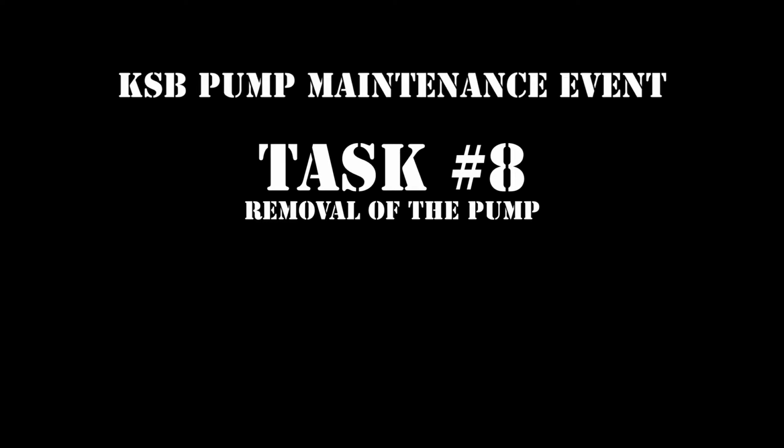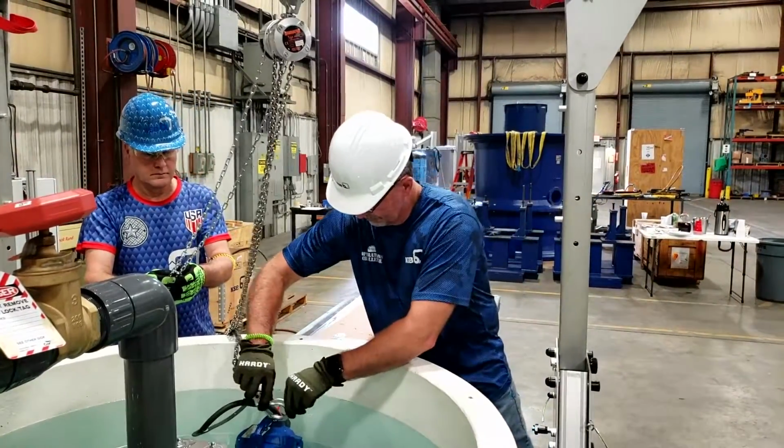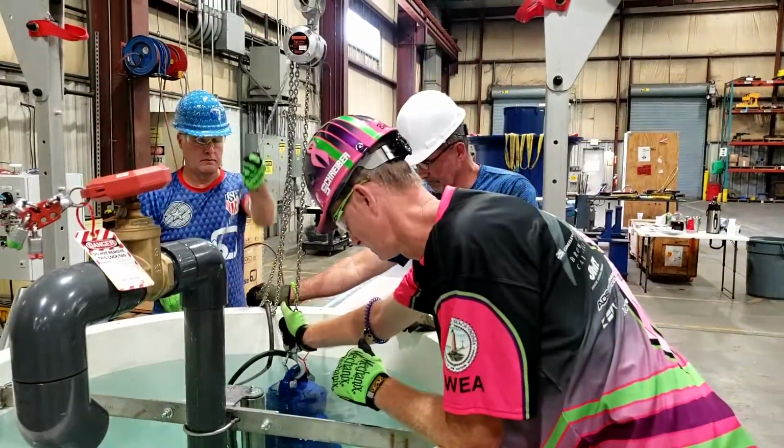KSB Pump Maintenance Event Task 8, Removal of the Pump. Once the gantry is in place and the wheels are locked, connect the chain hoist to the pump. Using the chain hoist, you remove the pump from the wet well.